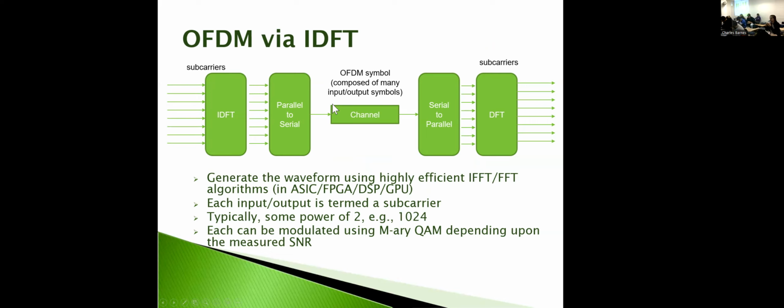In this simplistic model, not looking at MIMO, we have one channel. So we need to take all these. There might be 1,024 of these, or 4096 or something like that, right? And we need to take all those being processed in parallel and convert them to serial. So we just sample these in order and keep running around this cycle here. Then we send that over the channel, and then do the inverse response over here.